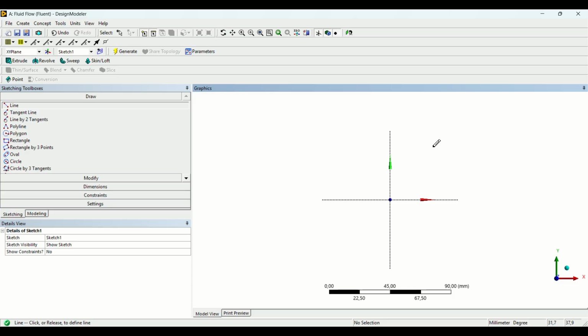And as you can see right now, the line is not straight, but it automatically will correct. See that I'm trying to create a straight line in the X-axis, so it appears the H, which means that it will automatically correct this small angle that I have. If I increase the angle, then I will create a line with an angle, obviously, and then I have to constrain it properly. In this case, I'm going to put a straight line. As you see, it automatically creates a straight line.